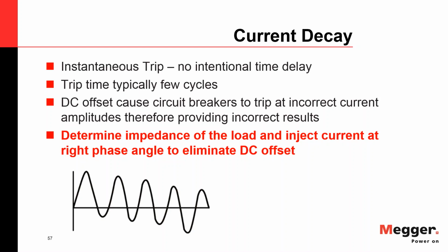On a symmetrical waveform, these two numbers are the same. If you measure the true RMS and you measure the peak and divide the peak by root 2, that should be the same number. If you have a fairly asymmetrical waveform, these two values are not the same anymore.